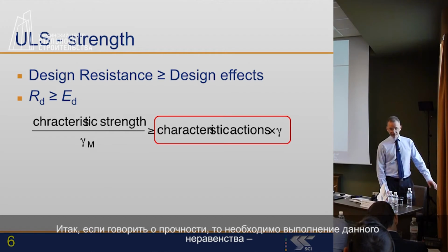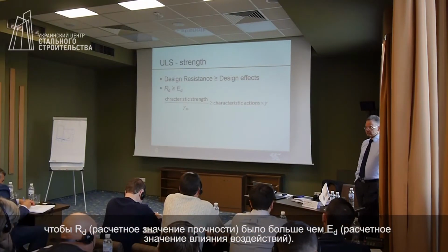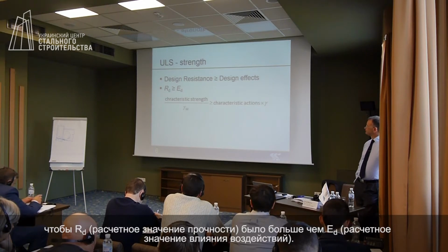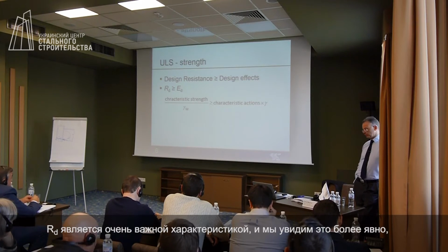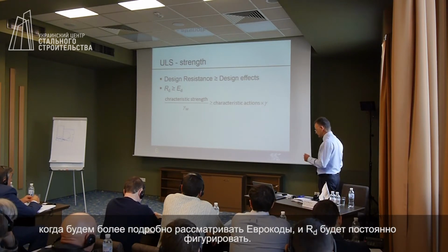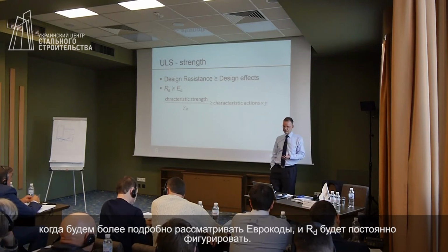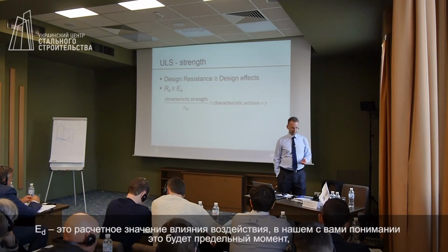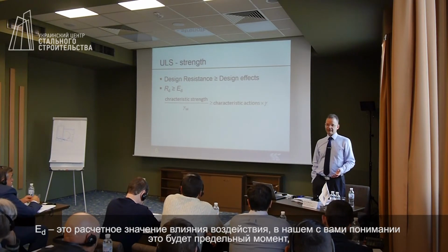So, as far as strength is concerned, we want RD to be greater than ED. And RD is a very important subscript. And we're going to see, as we get deeper and deeper into the Eurocodes, we're going to see these subscripts appear all the time. So, ED is the design effect.